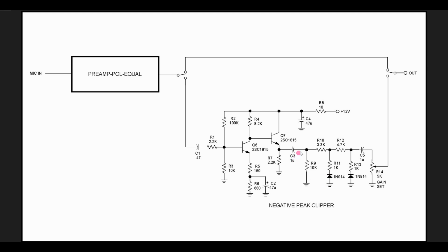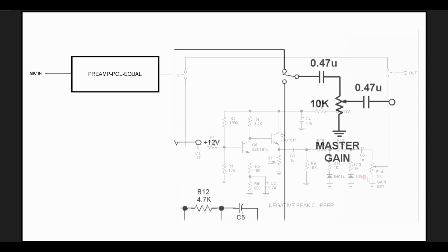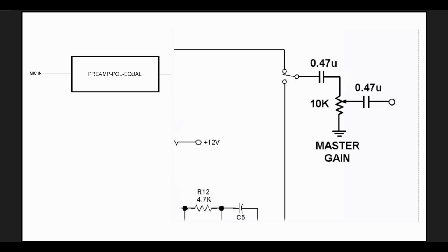It allows the positives to come against the diode, which is a backward bias diode, so there's no attenuation, but the negative cycle is attenuated and clipped at the level of the diode's forward conduction. So if you want a lot of clipping, you would use Schottkys here, like a BAT 85. If you want medium clipping, you can use some 1N914s or 1N4148s.